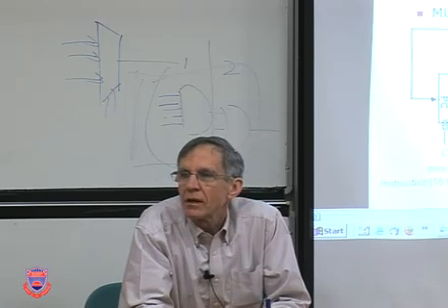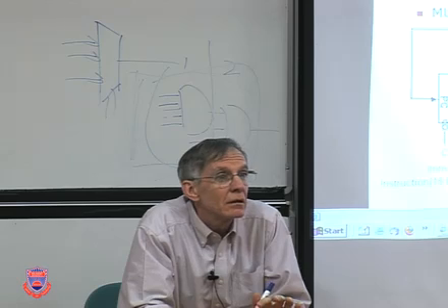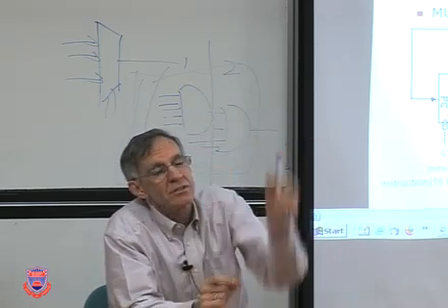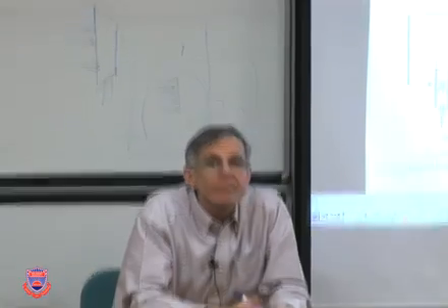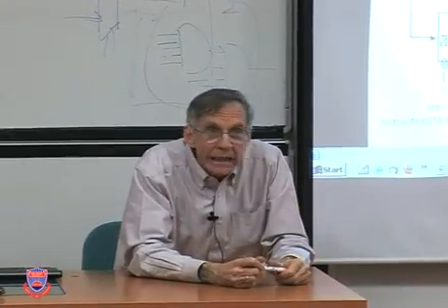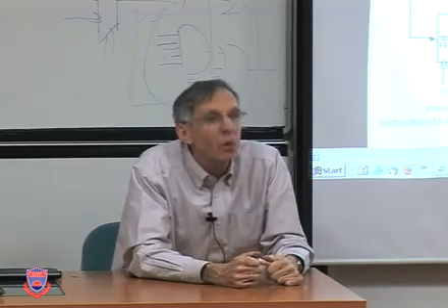What did George Boole say about Boolean switching functions? Come on now. Theory and practice have to stay connected. Please, friends. George Boole said any Boolean function can be implemented in 2 levels. It never requires more unless you want to make it slower on purpose. If you have reasons, you can make it more, but we can get the job done with 2 no matter what the switching function is.